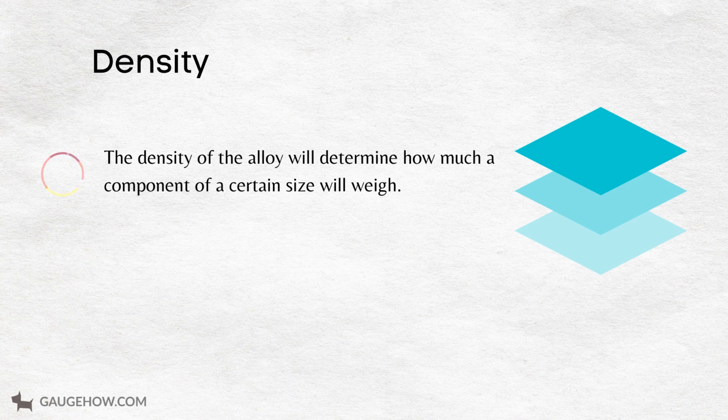Engineers looking for lower weight components may seek alloys that are less dense, but must then consider the strength to weight ratio. A higher density material like steel might be chosen, for example, if it provides higher strength than a lower density material. Such a part could be made thinner so that less material could help compensate for the higher density.